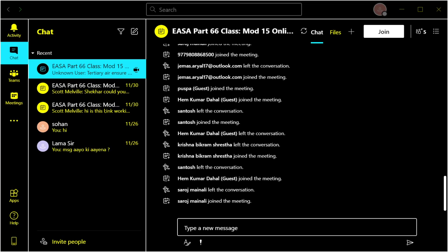So what is a bearing? Well, it's a device for locating a shaft with maximum radial restriction and/or axial restriction, but allows the greatest possible freedom of rotation. Very, very precision-made bits of equipment. Obviously very crucial. You'll soon know if your bearing's getting worn. Again, going back to your cars, your motorbike, even your push bikes, if the bearing's getting worn, it gets notchy, it gets gritty. It's bad enough on the ground, but in an aircraft, worn bearings could potentially lead to internal engine fires, which again, is not very good.